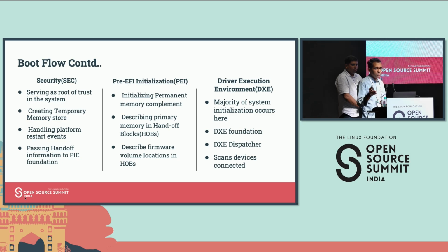So now moving into the driver execution phase, the DXE phase. This is where most of the hardware or platform initialization happens, where all the peripheral hardware gets initialized during this phase. It has majorly three components. We can say the DXE Foundation, where it starts certain services for the dispatcher and for the driver itself. There are a few core services that the foundation starts.